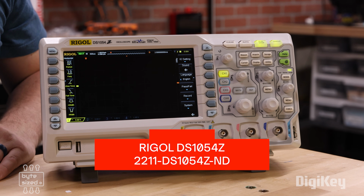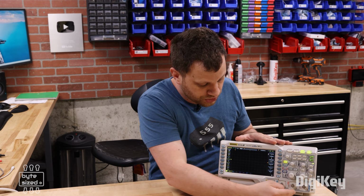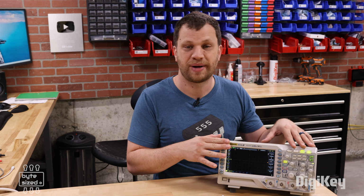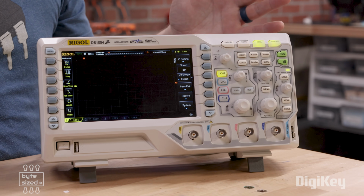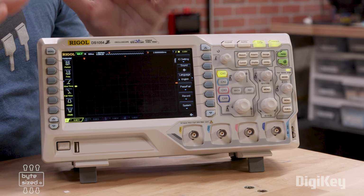I happen to have the Rigol DS1054Z. It's actually a great scope for its price point. It's got 4 channels, so you can measure up to 4 signals simultaneously. It's got a 50 megahertz bandwidth, although that's upgradable with a key, and it has a sampling rate of 1 gigasamples per second. At first glance, this front panel might look a little overwhelming. It kind of looks like a spaceship control panel with all the buttons, but once you break this down, it's not so bad.